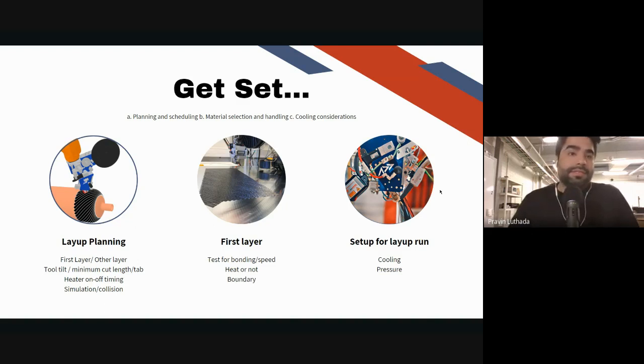Then the timings with the similar input that we got, and then check certainly for the collision at the tool level, more level, and then also see how the cabling is going to be moving around, and if you have it correctly loosened enough. It's slightly difficult to see with the collision simulation, but you can get an idea with the motion range of the robot that the cabling you have available at your facility is appropriate or not.